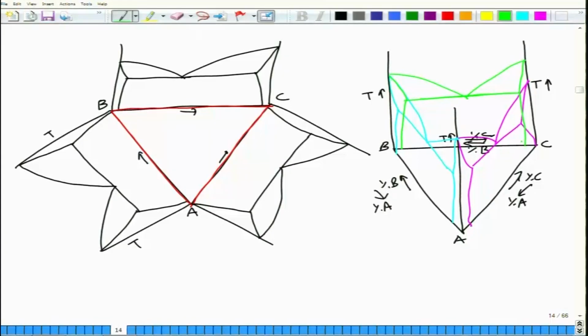There will be a top surface which is like a liquidus surface. It's like a curve. It's not a flat line, it's a three-dimensional curve. And within this you will have different phases now. So this is what is a ternary phase diagram. It's very complex to draw. That is why a ternary phase diagram is always presented as a pseudo binary diagram.